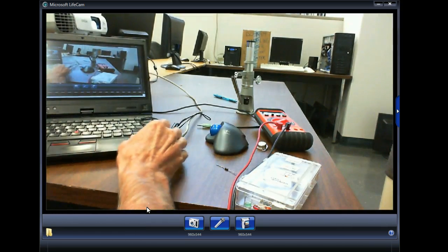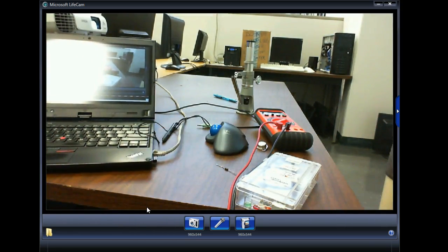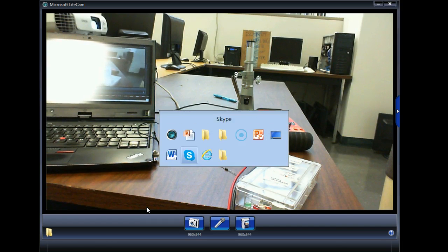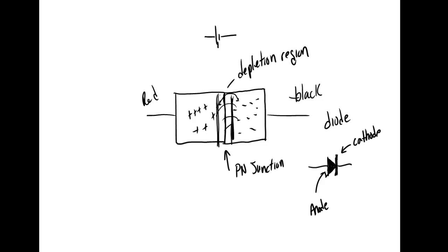And that's why it's got the diode symbol on it. We say we use it to check diodes, but that's not exactly true. We use it to check P-N junctions. So anything that's got a P-N junction in it, we can check with that meter just like that, which is a lot of stuff: SCRs, FETs, JFETs, BJTs, and of course diodes. And we have all different types of diodes. Right now we're looking at a regular rectifier diode, which is designed to convert AC into DC.